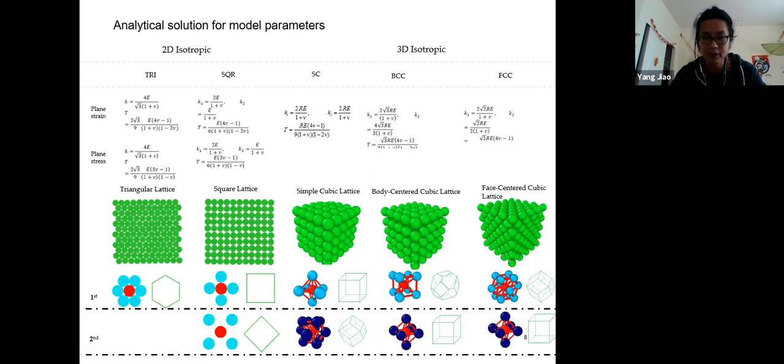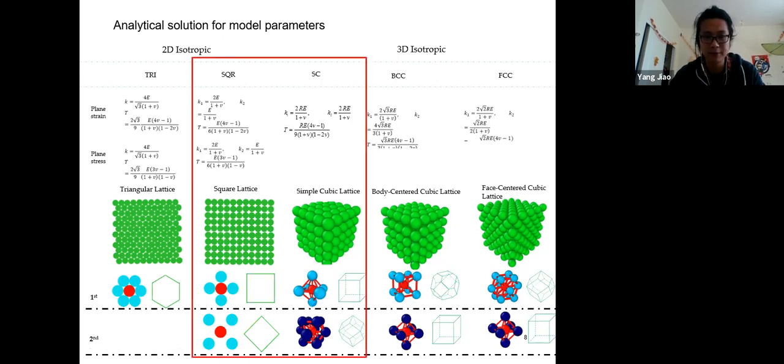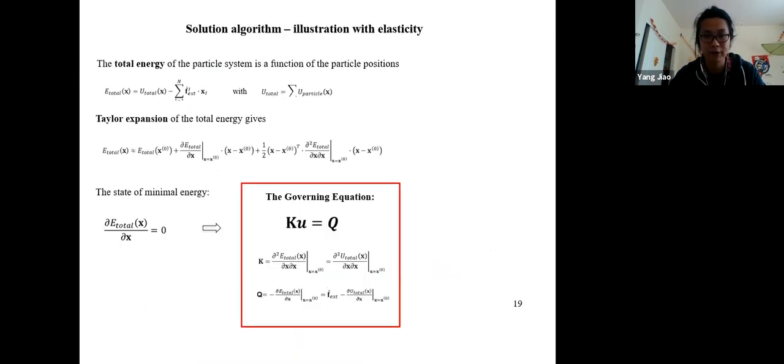But there's also a limitation, because in the derivation we assume that the deformation of the lattice is very small. We have similar considerations in the sweeping process as well. If your deformation is large, you will see deviations from this, which is a key concern in plasticity, but we'll address that later. In our case, we will mainly focus on the cubic lattices, which are compatible with our microstructure.